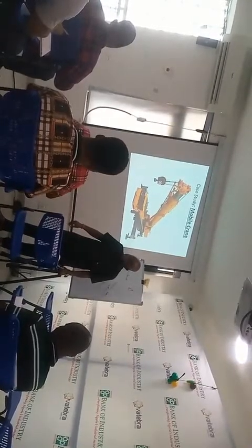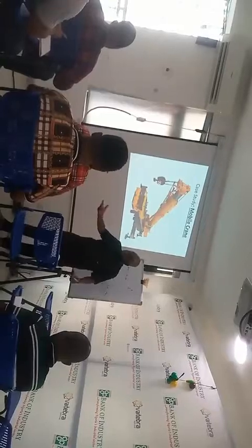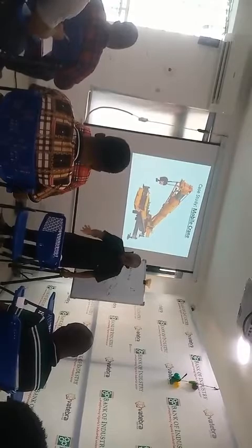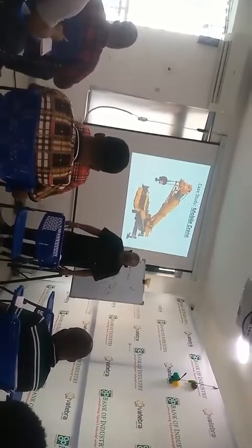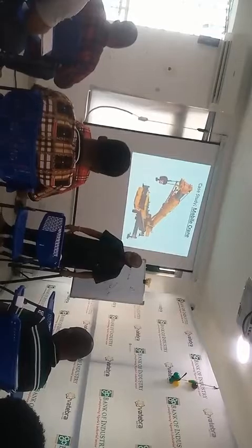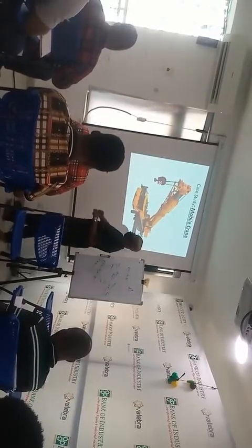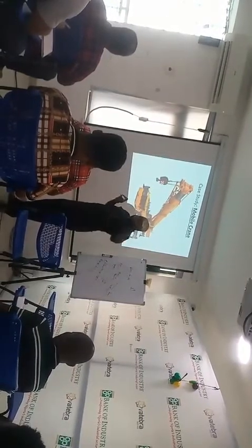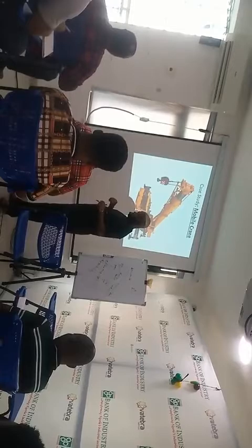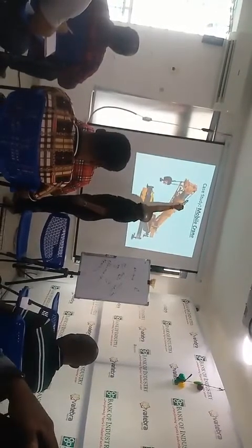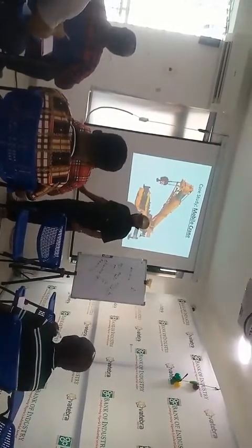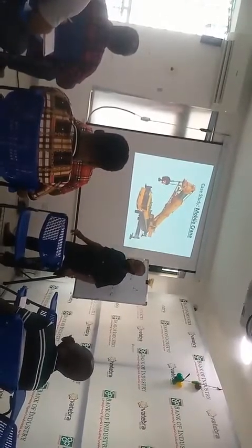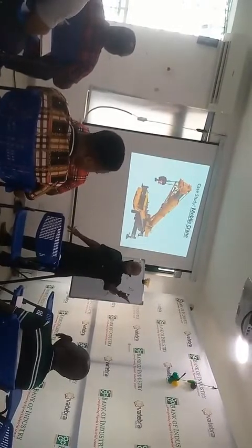Balance of the lift is also necessary, like you have also said when we are talking about balance. And it's associated with center of gravity, like I have already said. In some cranes, especially the offshore cranes, you will see something like a block here. What is the essence of that block? Just a very heavy block. For stability.